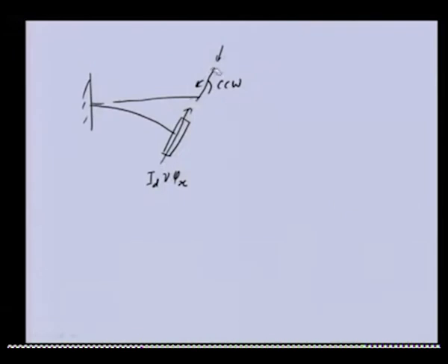So again I am repeating, the tilt of the disk when this particular disk is moving from time 0 to time dt is going inside the screen, and because of that the tilt about its diameter is taking place. If we look from the top, that particular disk is tilting in the counterclockwise direction. So this particular angular momentum is in the upward direction.